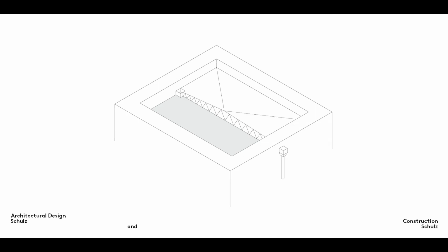In the opposite case, water is removed externally via a downpipe, as for a pitched roof, rather than internally through the building. Here, the lowest point of the roof is at the upstand and its highest point in the center of the roof span. The upstand needed in this case is lower than that required for a central rainwater outlet and internal drainage.